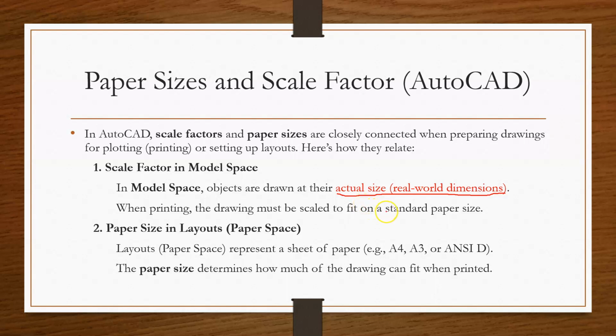But in model space, for the most part, what this is actually telling us to use is assuming that we're going to be doing things in paper space and model space. But if you worked before we did the paper space thing, you can also get away with doing this in model space, but that's where that rule is going to apply. If your drawing and your title block is going to be housed in model space, then you have to use an exception to this rule. But if you're going to be using paper space as a means of doing your drawing, then everything that you create in model space will have to be the real size. That's going to be the representative of it, right?